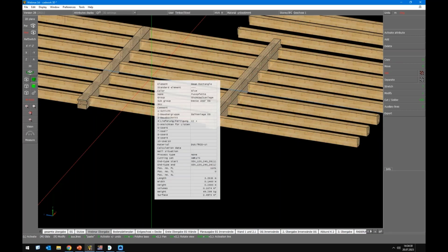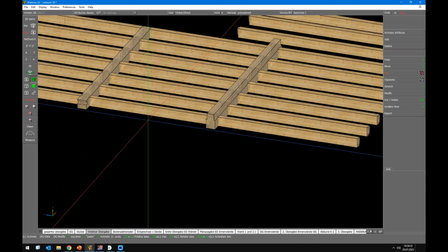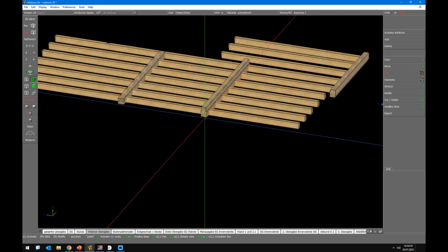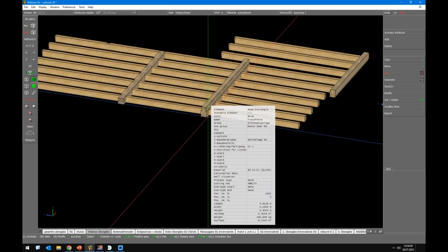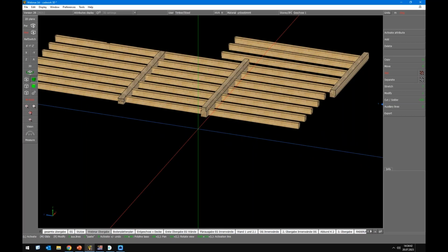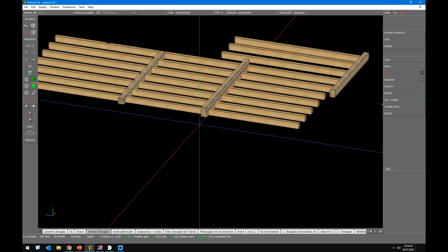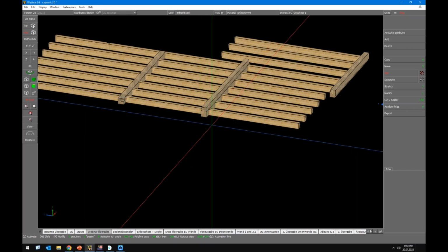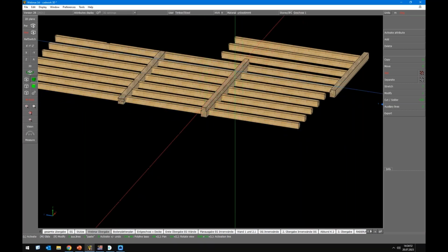So in this case we need to think about the cross-section height, especially as we do not have so much height in the floor. So when we have at least, let's say, 2.50 meters and the downstand beam has already 400, then only 2.10 meters are left. And of course, this is less. So in this case, we need to keep the downstand beams as small as possible.